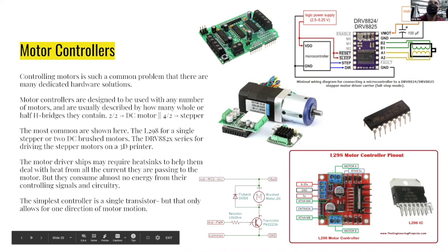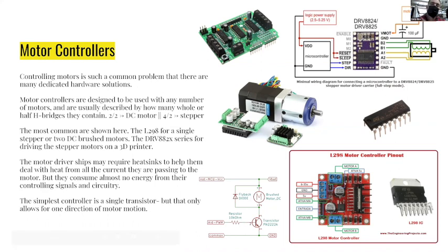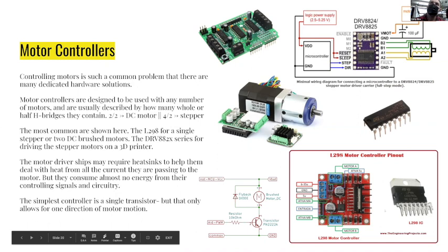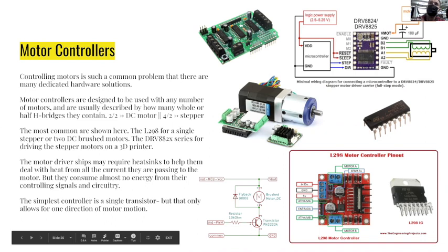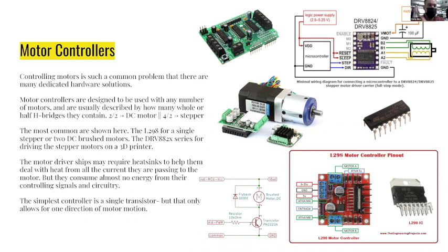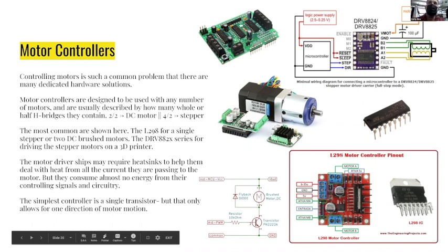If you've got an L298, this is the classic, probably not the oldest, but one of the older chips that will drive a motor. These little motor controller boards are really helpful. You can plug in a motor here, you can plug in a motor there, and then put in your power. And then all you need to do is put in signal for if you want it to go and if you want speed control and some of those things. You put in on a couple pins over here, but this handles lots of the logistics for you. There's some current regulation, capacitors to smooth things out, to deal with the stall current, and lots of different pieces.